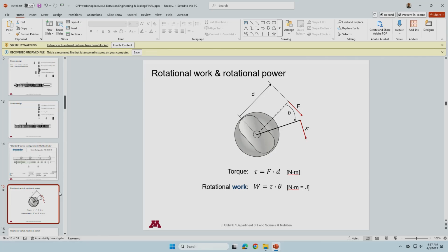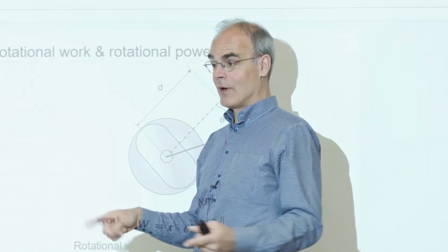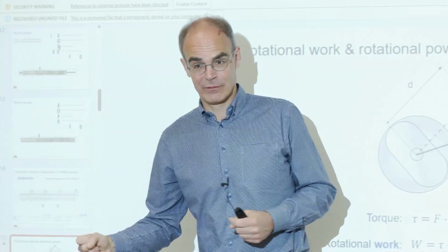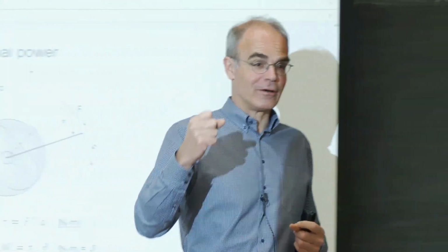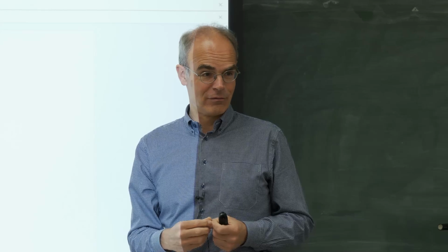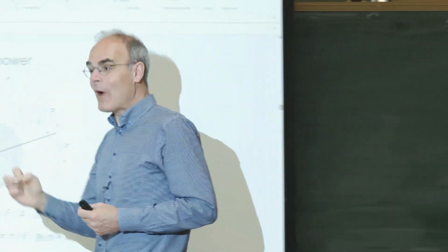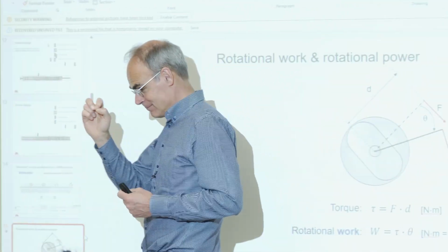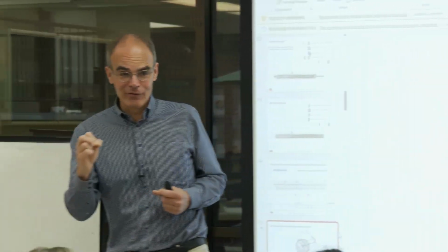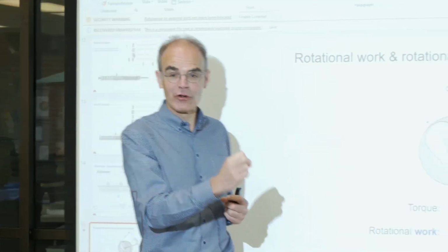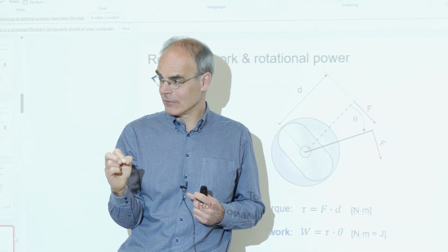So key thing, in extrusion, we start to apply mechanical forces. So it's a thermomechanical process. Yeah? We heat it up, that's the thermal part. And then we have the mechanical forces that we shear it. How do we apply shear? Over these screws. Yeah? What is the fundamental way we're exerting work on that material in the screws? It's by turning the screws. What is the measure for that?